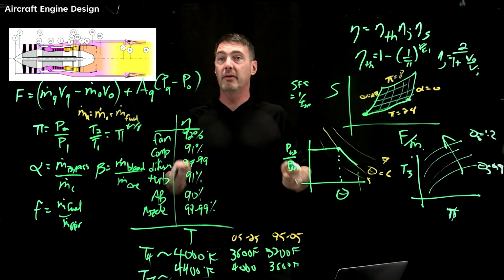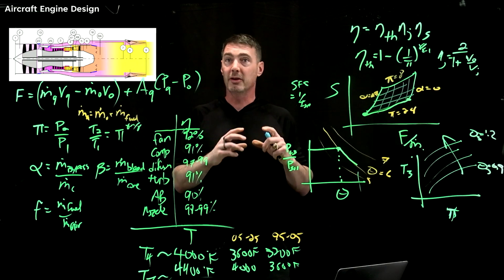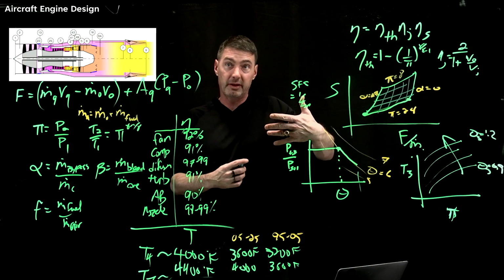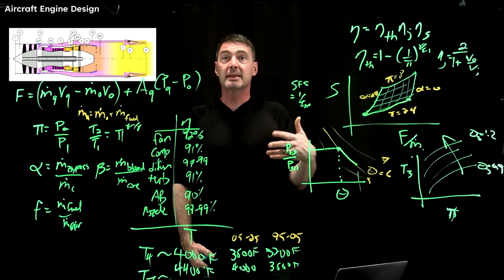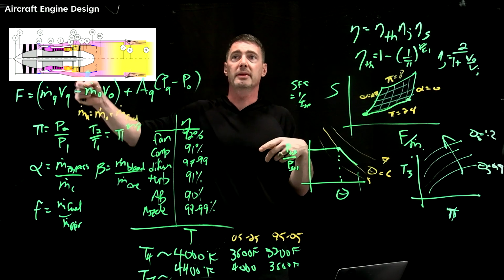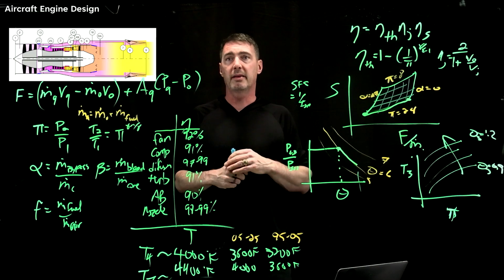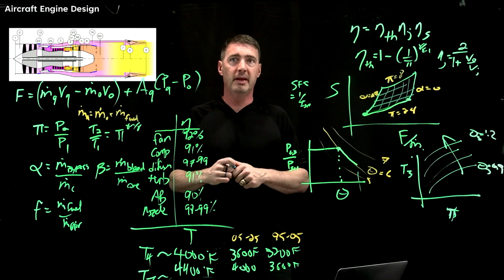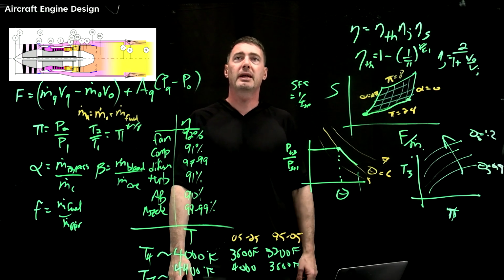Okay, so if you're a pilot, that's why a lot of times turbine exit temperature is one of the sensors you're going to have in your screen, and some of the automated systems will just follow it. It's one of those things you're going to pay attention to as a pilot, that turbine exit temperature and how hot it is. Because if it gets too hot, that's the sign that something upstream is getting too hot. All right, so those are your main performance characteristics.